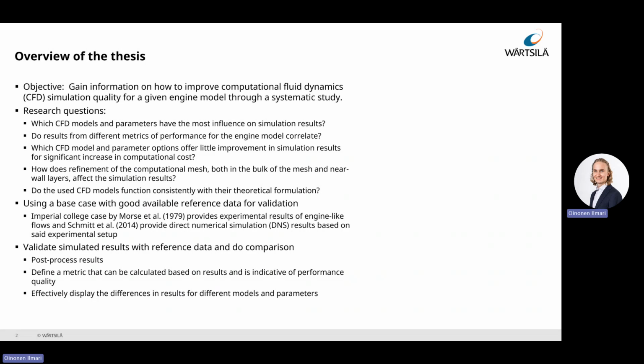The posed research questions are: which CFD models and parameters have the most influence on simulation results? Do results from different metrics of performance for the engine model correlate? Which CFD model and parameter options offer little improvement in simulation results for significant increase in computational cost? How does refinement of the computational mesh, both in the bulk of the mesh and near wall layers, affect the simulation results? And do the used CFD models function consistently with their theoretical formulation?